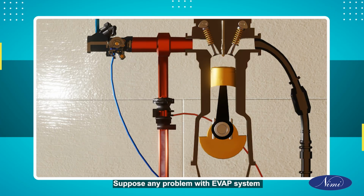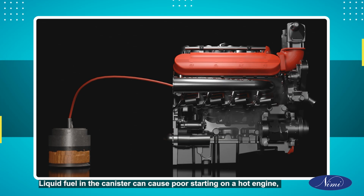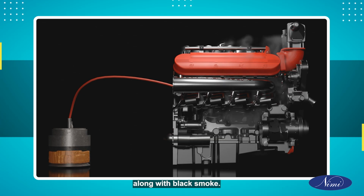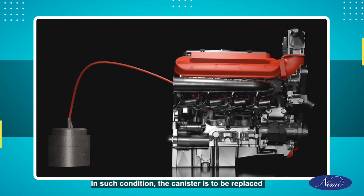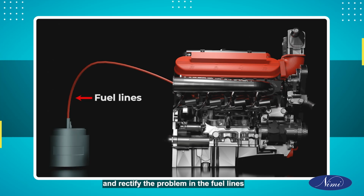Suppose there is a problem with the EVAP system, such as the purge valve being stuck open; it results in high emissions and a rich mixture at idle. Liquid fuel in the canister can cause poor starting on a hot engine along with black smoke. In such a condition, the canister is to be replaced and the problem in the fuel lines rectified.